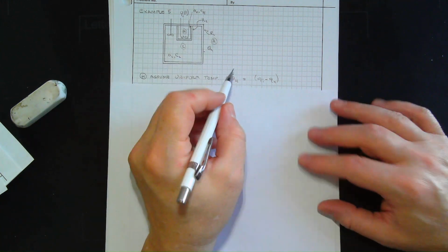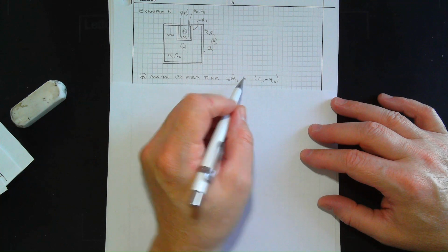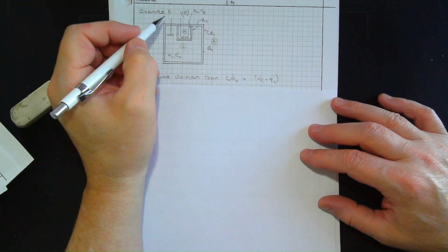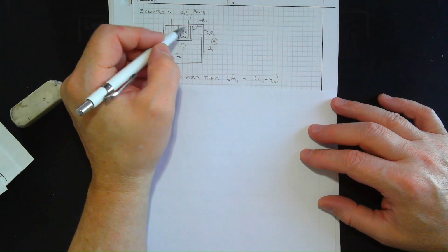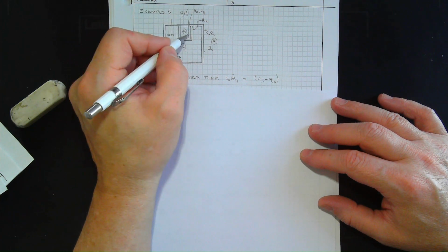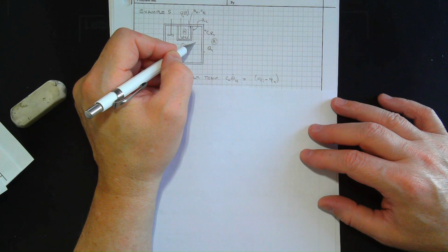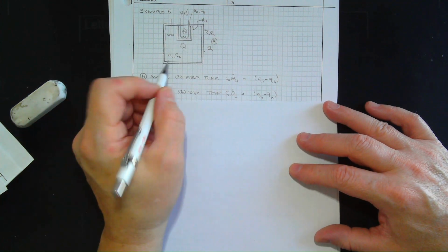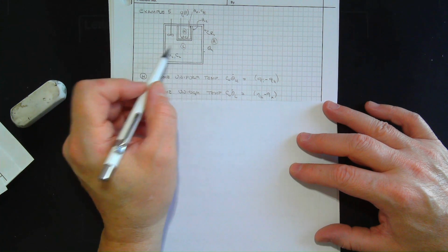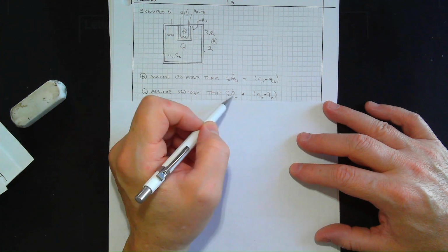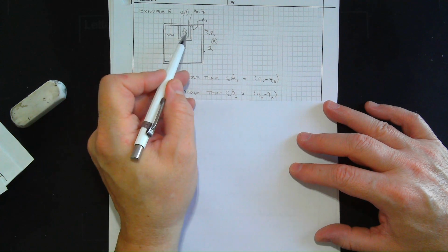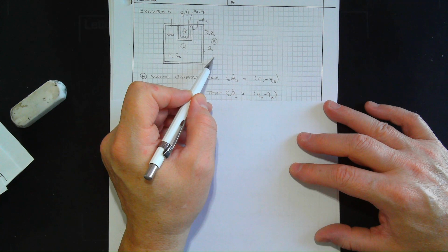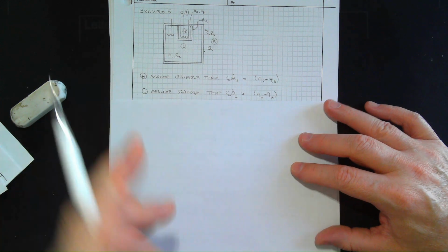So we have CH theta H dot equals heat in minus heat out. I'm calling QI the heat that's being supplied, and QH is the heat that leaves out from here. All right. And then, again assuming uniform temperature here, we have CL theta L dot equals the heat in, that'll be QH coming across, minus leakage to the ambient atmosphere, so minus QA.